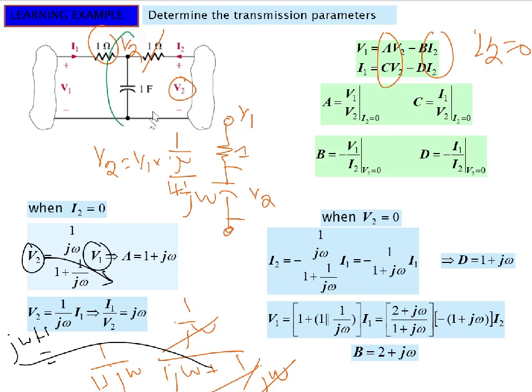If we check this circuit, here we have V2 in it, and the current that is flowing through this circuit is I1, because the same current is flowing in this circuit. The impedance of this circuit is 1 over j omega C. C is 1, so 1 over j omega. So we can write V2 is equal to 1 over j omega into I1. So directly this is solved.